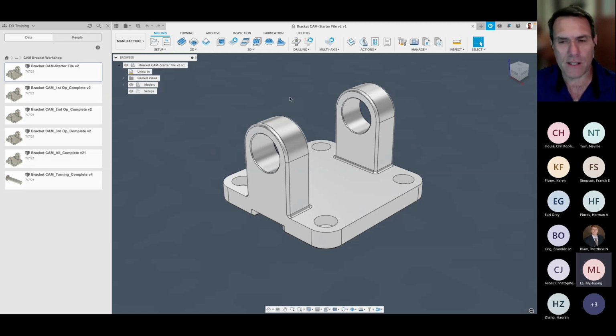One of the things that's important to know about doing an initial setup is that the setup is declaring what the material you're going to start working with is, how it's going to be oriented on the machine, and giving it a name for the G code so that when you're creating unique programs for the various setups, it's easy for you to tell which one is which.